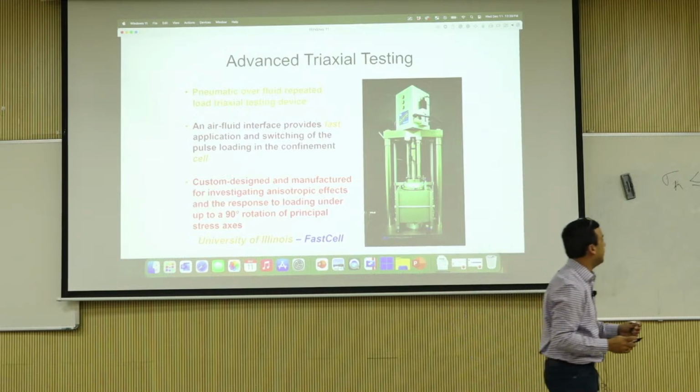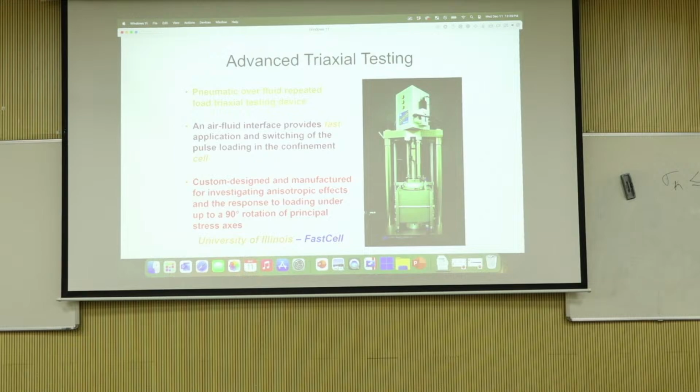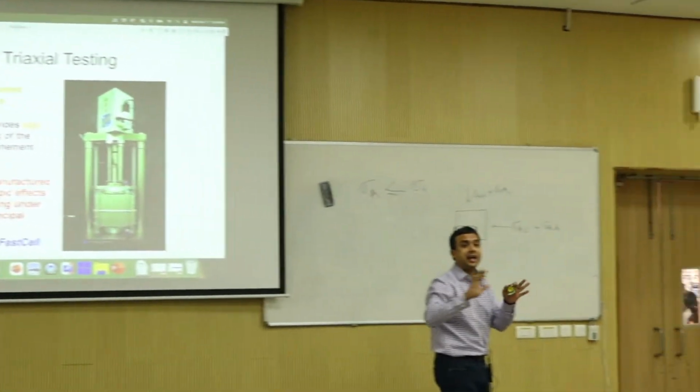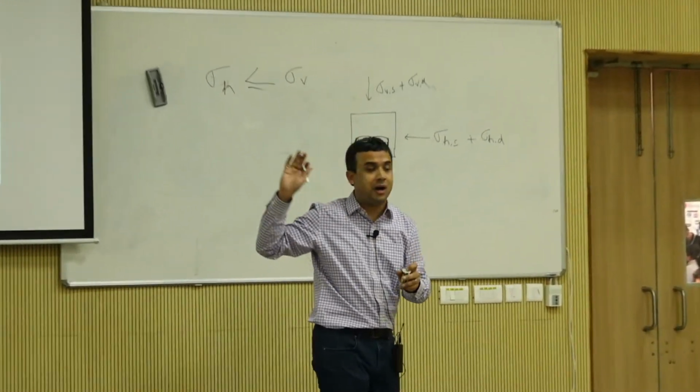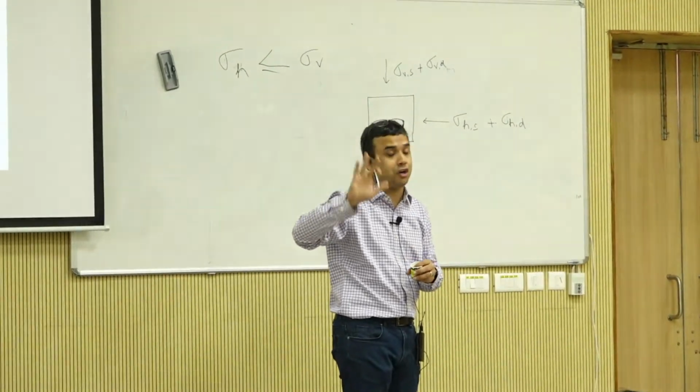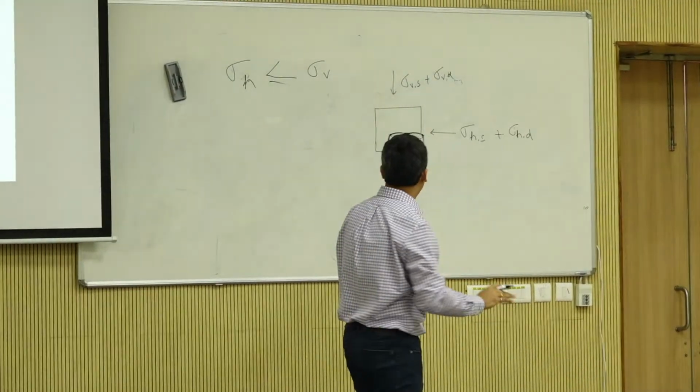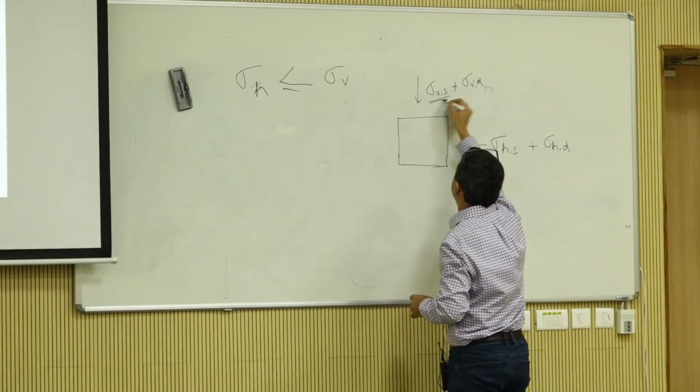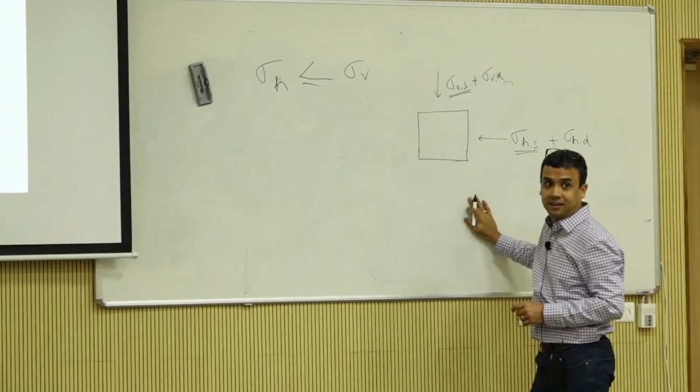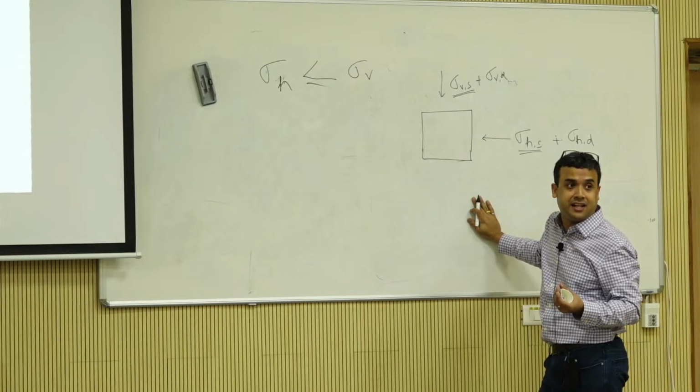Now what can I do? If I want to run a standard, conventional triaxial test that you have been running, and we are talking resilient modulus, not shear strength, resilient modulus, what should be the relationship between sigma Vs and sigma Hs? S stands for static.